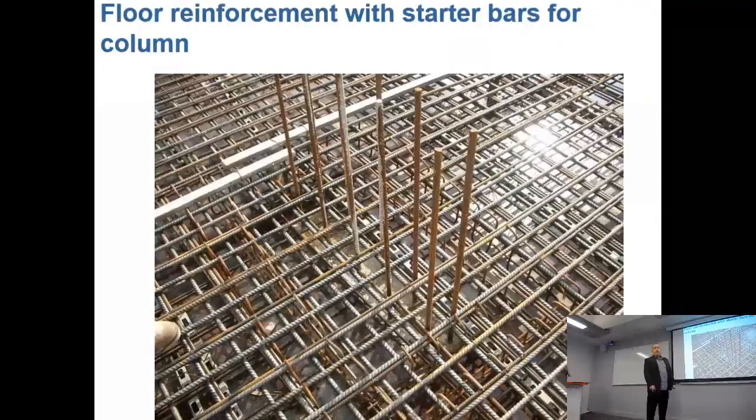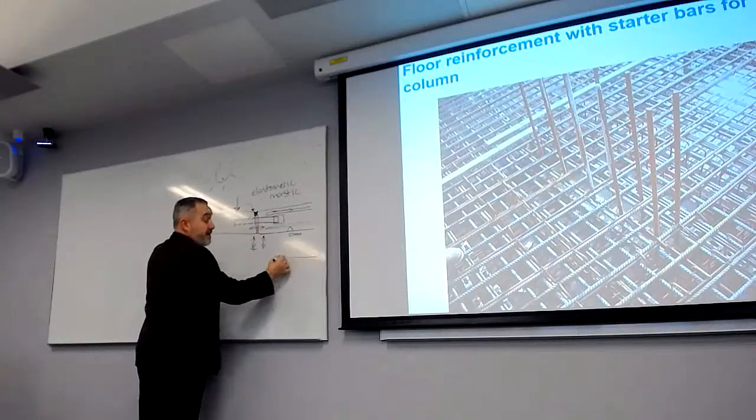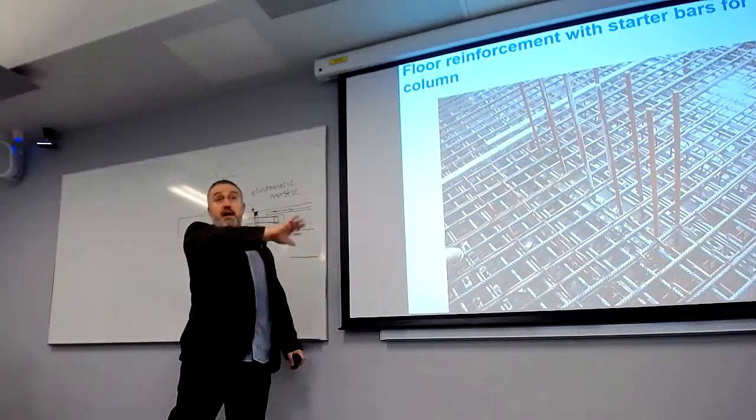What determines the length of the starter bars? The length of the starter bars is based upon the Eurocode 2. So next year you get a detailing guide. So you've got everything about how long these should be, or if you've got a really long floor slab and